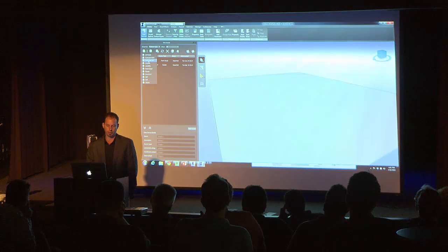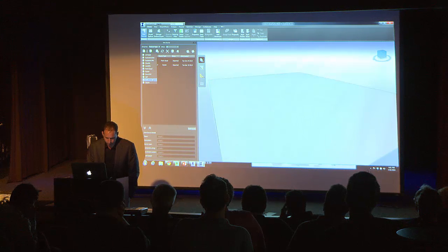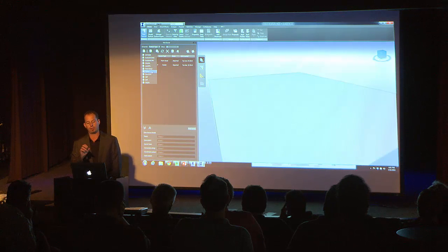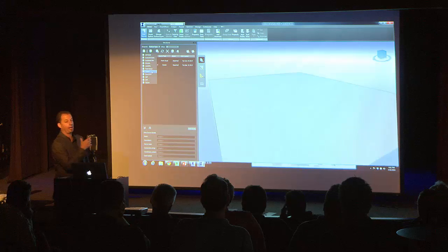All you're going to do is look through here and look for the data that you want to include. So if we look in here and we want to add SDF or shapefile, whatever the information is, if you're looking to bring in a surface off the USGS website, you actually want to go to raster.